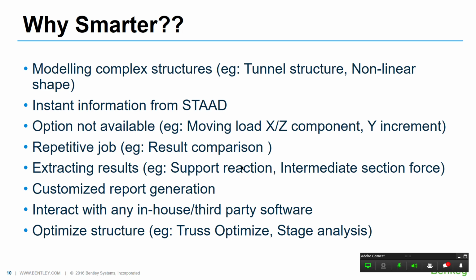So for example, consider an elliptical structure or a dome structure. We know the equation of that ellipse, or we know the equation of the circle or dome. If we can write our code there, we can create some inputs about that particular ellipse, or the dome or the circle. We can write some math functions, so that those particular geometry points will be created, and those geometry points can be imported instead using this particular OpenSTAAD function.